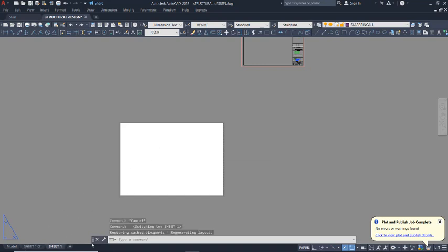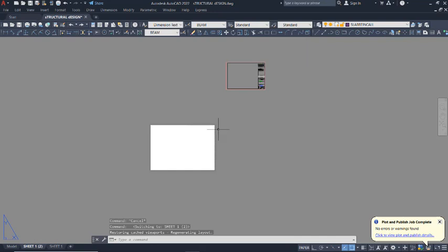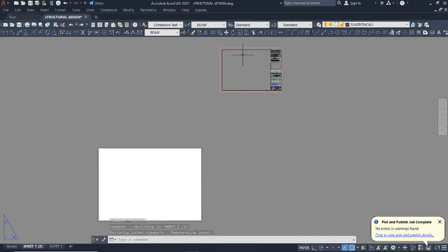So as you proceed to create multiples of a sheet or paper space just like this, let's get over to the first one right there. Okay, so we want to fit this title block into this paper space, so that we can plot our drawings to a specific scale.